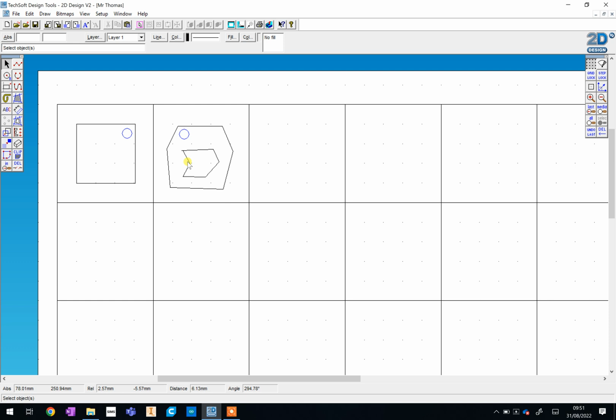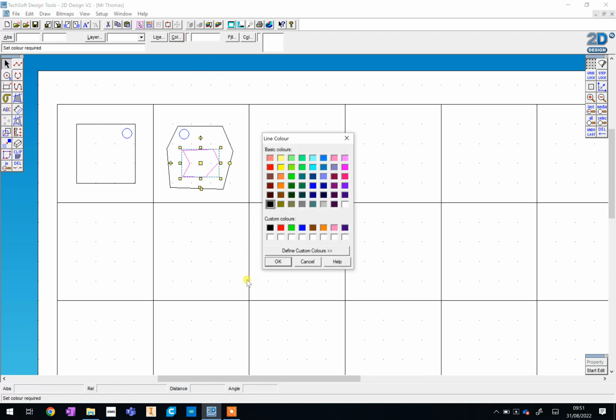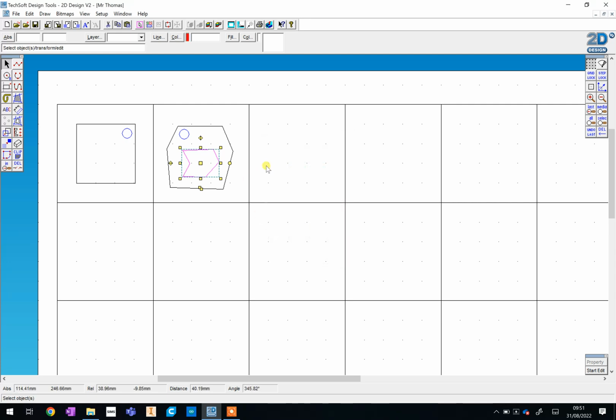And at this stage, if you want it to be engraved, we select the shape. And again, you can do that just by dragging your mouse over it. We can then go to color. And remember, for anything you want to engrave, that's just etching it on the surface, burning it on the surface of the material with the laser. Then we select red. And now we've got a design that's got an outline shape, a hole, and it's got engraving. And these are going to be the designs that are going to get a few more marks and a higher grade overall.